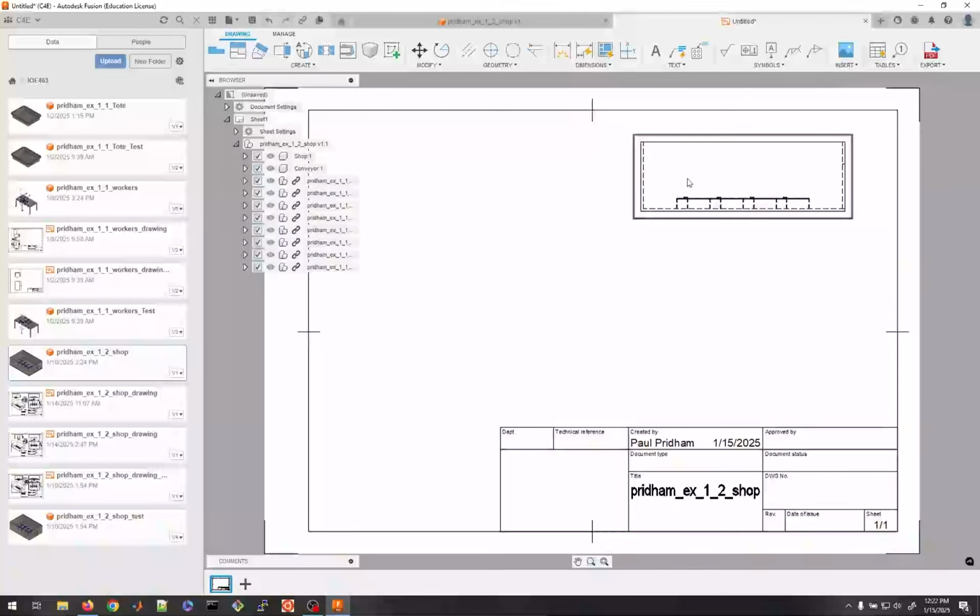And you can see what I was saying about the hidden line. So you can see the conveyor and the benches. Normally you don't do any dimensioning on hidden lines. So if you wanted to dimension, say like the height of the conveyor for this, we could come up here and do section view, cut a cross section of this view, and then that would allow us to see the hidden lines and we could dimension off of that. But we don't need to do that for today, so that's just an additional tool that's good to know about.